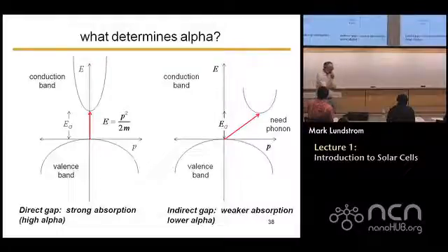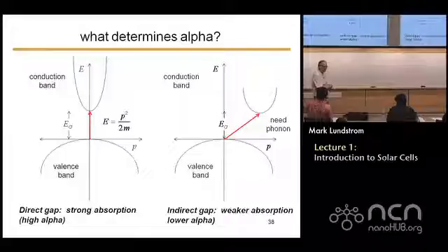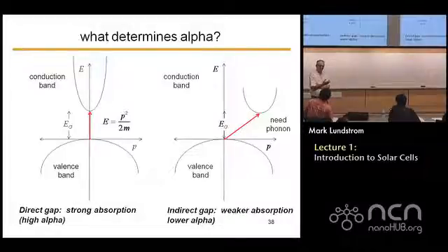Yeah, I'm not sure I exactly understand the question. There actually is a direct band gap in silicon, right? There is a conduction band up there at higher energy, and the higher energy photons can be absorbed by that direct process. My question is, direct band gap is better or indirect band gap? Which one is better? Oh, I think direct band gap would be better, because everything is about cost. Even if you can minimize the materials cost and you can absorb all of the photons in a very thin layer, it's always best to have a direct gap.